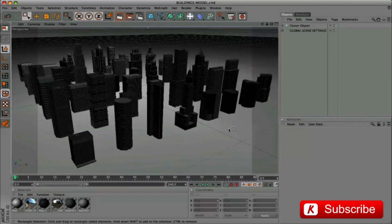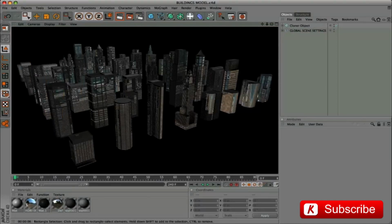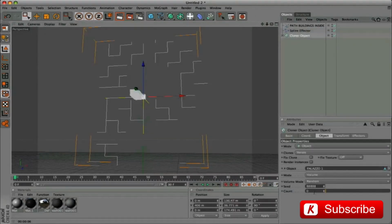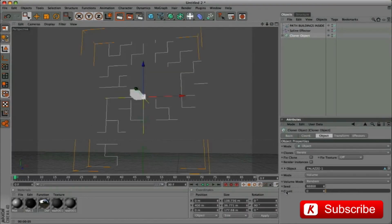Go to the reference file with all models, and select the models that we want to insert. This technique will allow you to insert all the models you want, 10, 30, or 100. Obviously, with many models, the file will become heavier, and the rendering will be slower. We will use the MoGraph module, the Cloner object. In my project I use 20 models of skyscrapers.